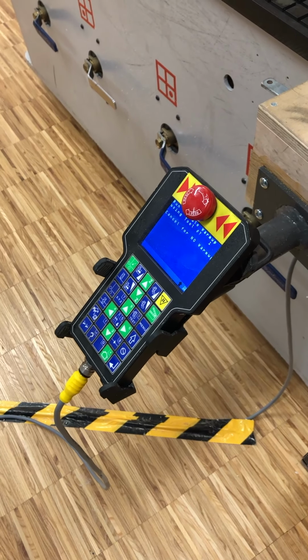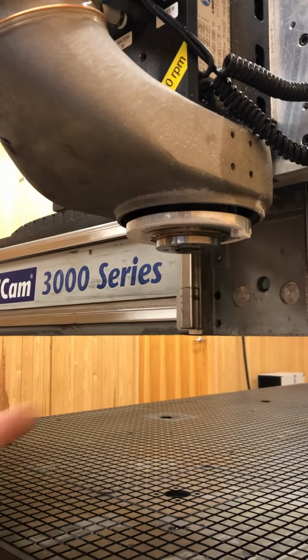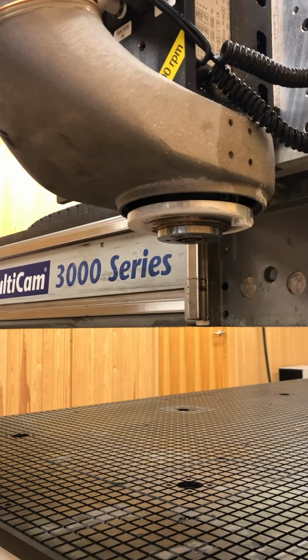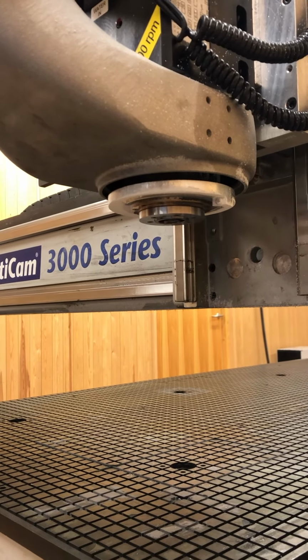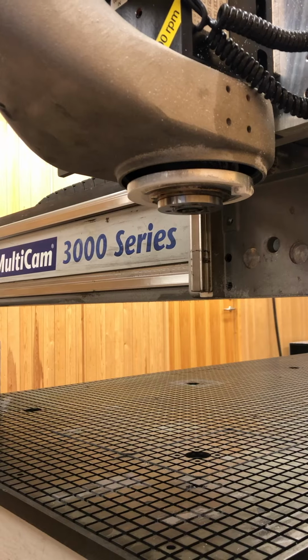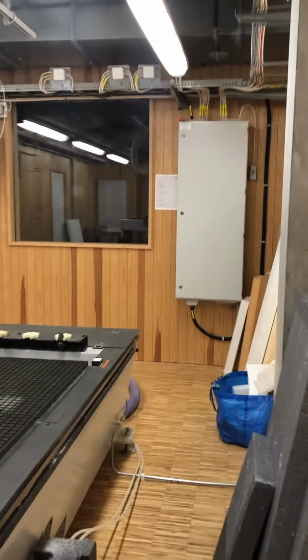Without clicking here right now, we will now choose a warm-up tool. The purpose of the warm-up is to warm up the spindle. The tool that we use should be as small as possible so as not to put another load on the spindle. So we can go back here and see what tools we have.